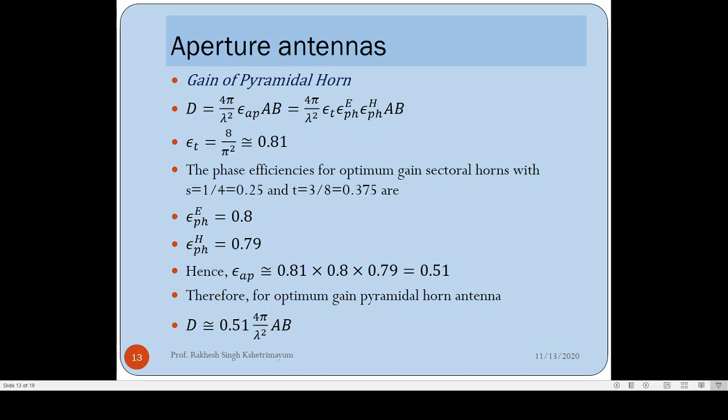So we are designing this horn antenna to improve the directivity of the open-ended waveguide. Basically, gain is a very important parameter for the pyramidal horn antenna. So we have changed the open-ended waveguide by flaring it out to make the pyramidal horn antenna, to improve the gain of the horn antenna. So gain becomes a very important parameter for the horn antenna.